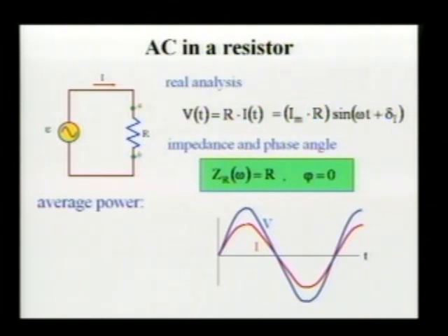Nope. I mean, in general, not just for a resistor. It's true that for resistors we can multiply square of current by resistance, we can divide square of voltage by resistance. But in general, it's a product of current and voltage. But this gives us instantaneous value of power, not average power, Adam.